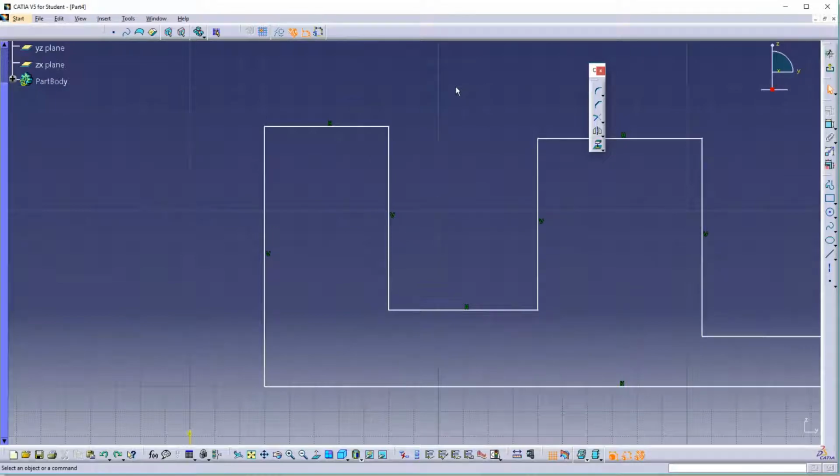I'm going to show you how to key in a value for your corner. Let's select the corner option. Let's pick 1, 2. Now you'll notice up here is a radius value. Now a lot of times people think they have to come up here and select in the box. But I'm just going to be down here like this, and I'm just going to go to my keyboard and type in 20. Enter. Okay, so you don't actually have to leave your keyboard to come up here to do that. Okay, Control Z to back out of that again.